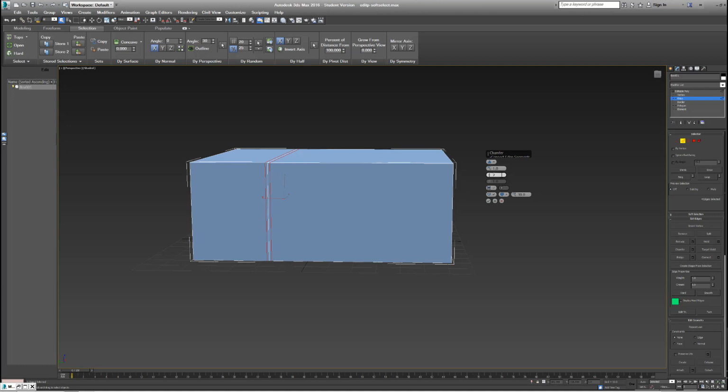This is the amount of lines between my 2 red lines. And I can do that by either typing in a number, say 4, hitting enter, and you see 4 lines have appeared. I can go back to 2. No big deal. Or I can click and hold and drag that number up and down with my mouse. So a little bit easier to control. I kind of like doing that because it makes it a little more organic, a little bit more free-flowing.